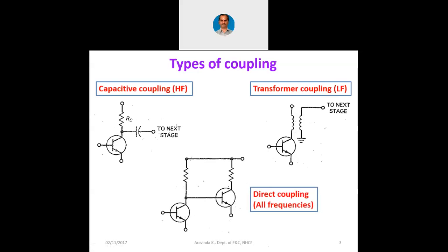Now this is called direct coupling. In the sense, you can see the output at the collector is directly connected to the base. Generally, an operational amplifier internally is a direct coupled amplifier. That means inside the operational amplifier's integrated circuit, there are no coupling capacitors at all. So that is a direct coupled amplifier. Whatever changes happen here at the collector of the first transistor, they get reflected at the base. But the point here is, when the signal is not present, the DC is also present here.